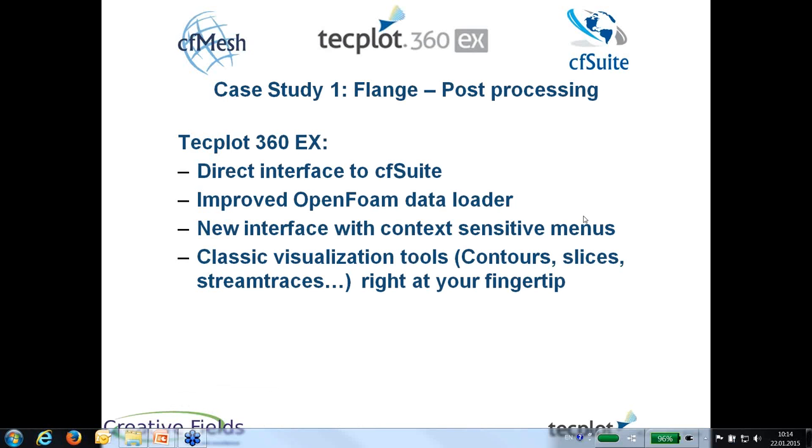So regarding the post-processing, it will be done within 360X. We've got a direct interface to cfSuite, as you just saw. We also have an improved OpenFOAM data loader. Our new interface allows actions such as context-sensitive menus, accessible on right-click, for example. And I will show you all the classics of visualization, such as contour slices, trim traces, and so on. And they're all right at your fingertip, as you will see.